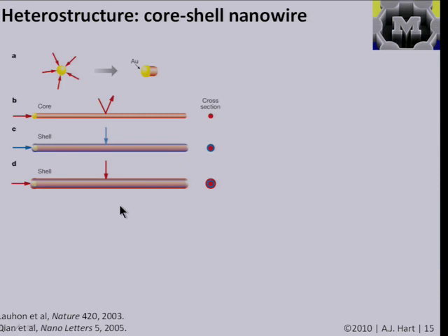And there are also ways, as we'll start to talk about synthesis later, to create what are called heterostructures, or combinations of materials, or things that may not directly come from the way the material self-organizes. And this is an example of what's called a core-shell nanowire. So made by a process like I briefly overviewed last time, where you imagine we're all sitting in a big furnace and we spray in some small particles of gold, so some gold nanoparticles. And remember, we fill the room with a gas that contains silicon, this material that we want to grow, and basically start producing a nanowire using this gold particle as like the little reactor.